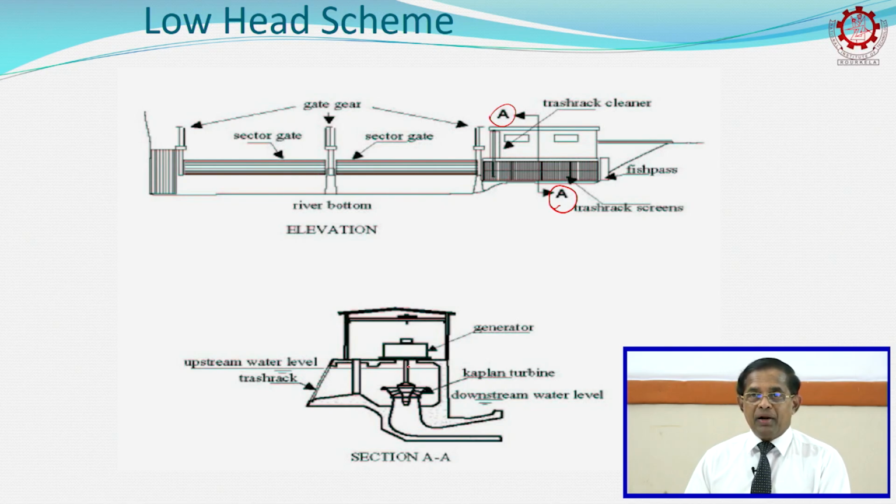So, in hydropower plants you will see both configurations, horizontal axis as well as vertical axis. Especially in large hydros, it is a vertical axis arrangement, because if you have a horizontal axis one, the weight of the generator, weight of the turbine, etc., will be too much on the shaft, because they are very heavy and the shaft might deflect, right.